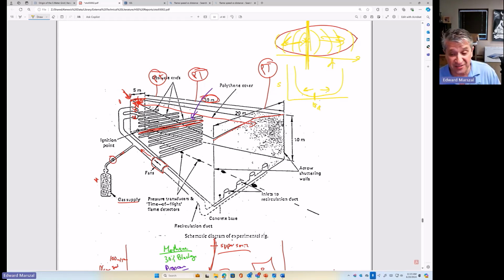And the unsatisfying answer is any gas cloud can cause harm. Any gas cloud that is above the probit value for fatality, or the probit value for serious injury, can cause harm. Now, if you go with a philosophy of, I want to detect every gas cloud that can cause harm, you will not be able to walk through your plant, because you'll be putting gas detectors every 10 centimeters, which is not realistic.